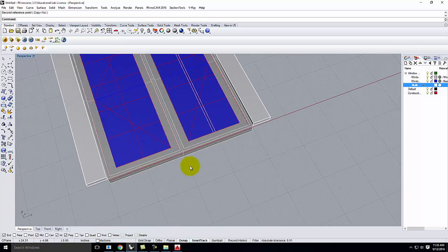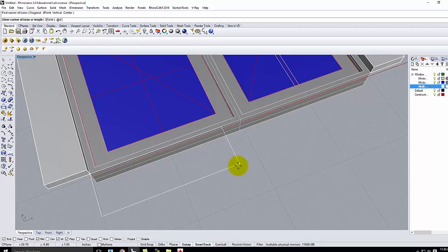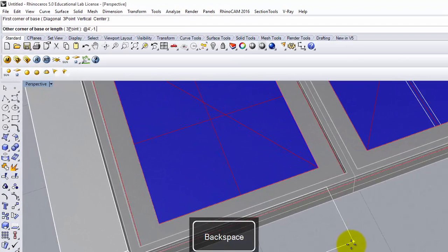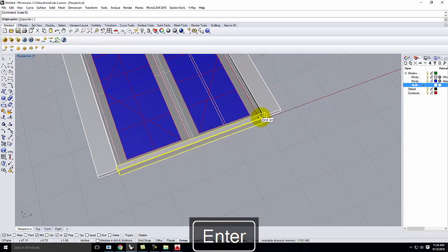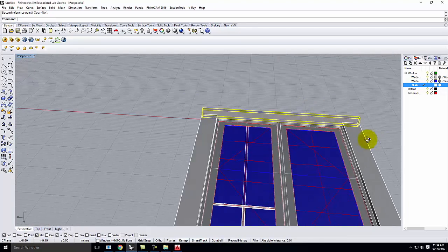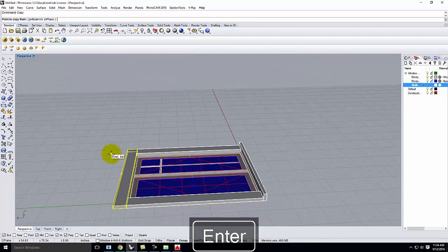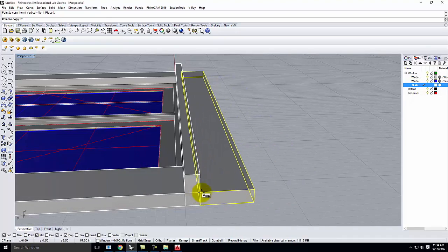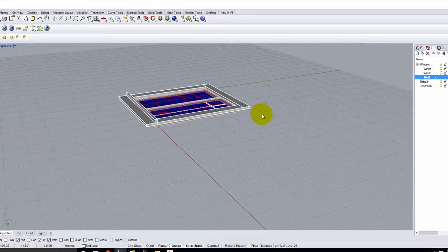Let's add a little sill at the bottom. So this was at 4 feet, comma, negative 1.5 inches. There we go. And let's have it stick out a little bit more. Let's go maybe 3.5 inches. Scale 1D. And I can pull this all the way out like that. And then I could take this piece and copy it to right there. And now we'd have, if we were looking at it, what the exterior trim would look like on the window.